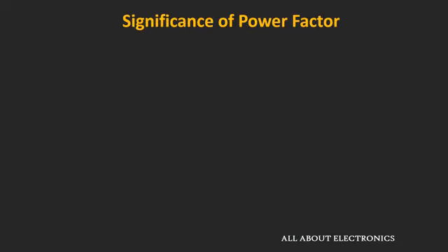So when we have a poor power factor, it means we are drawing additional power for the reactive element across the load. And this additional power means we are drawing an additional amount of current. This additional amount of current will introduce a voltage drop across the cables. That means we will receive a lesser amount of voltage at our homes and offices. So all this is basically an additional burden on the power supplier.